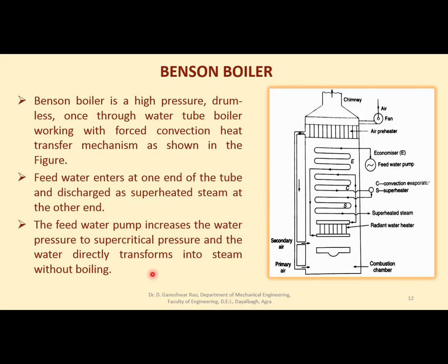If you remember the steam properties taught in first year, at the critical point there is no requirement of latent heat of vaporization, and the entire water gets converted directly into steam without boiling. So if that pressure is attained, then without any input of energy, the entire water can be converted to steam. That principle has been used in the Benson boiler.